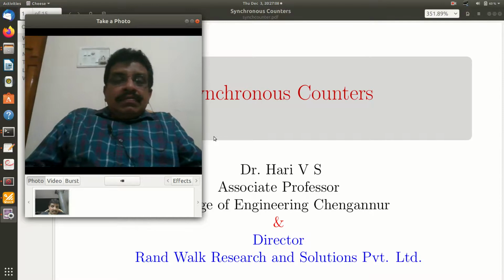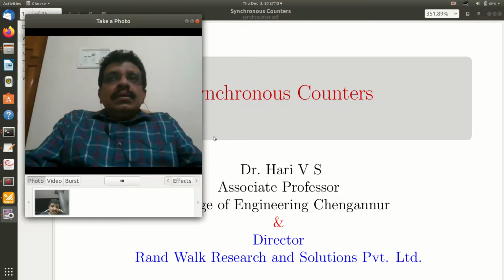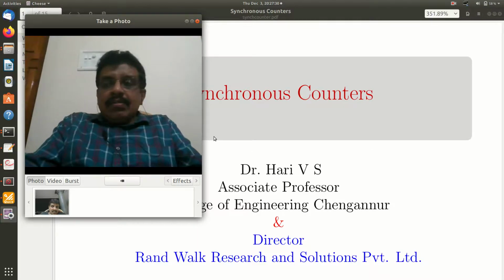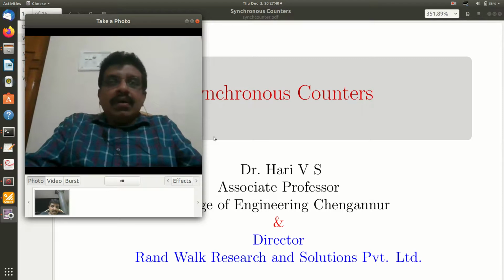So in the last few classes we have understood the ripple counter. In that, you know that the first T flip-flop is clocked by the external clock, and the succeeding flip-flops are clocked by the previous outputs. The clock ripples through this ripple counter, and if there are n stages, it takes (n minus 1) times the delay of one flip-flop for establishing a count. So this is very time consuming.